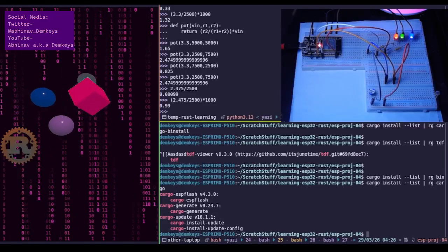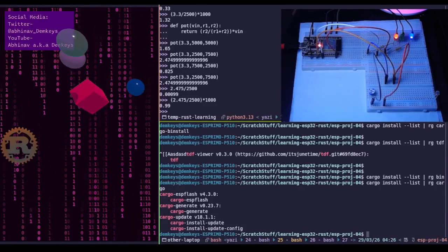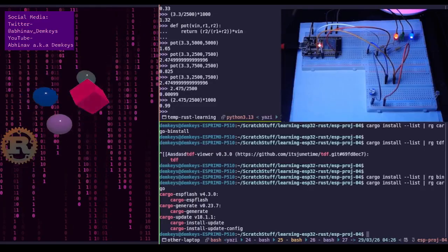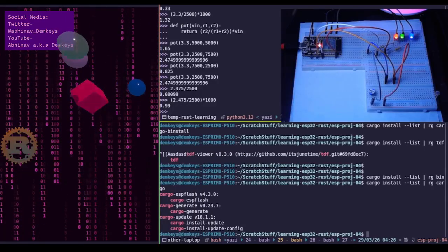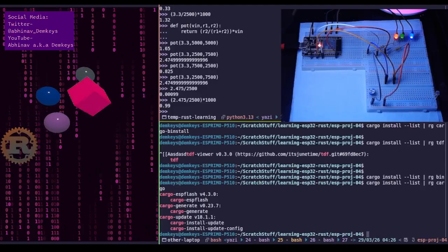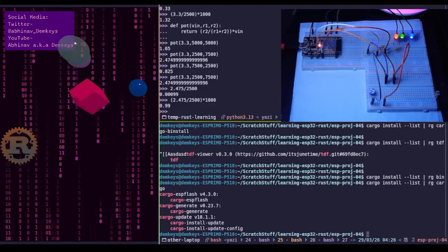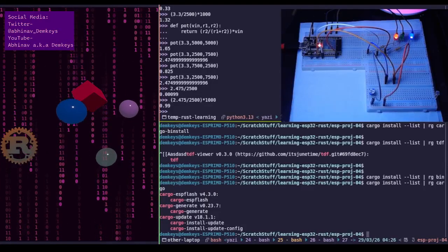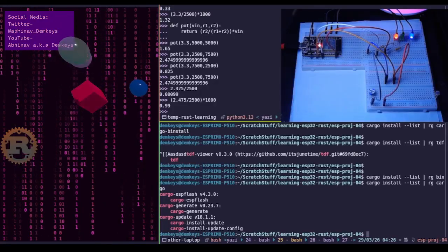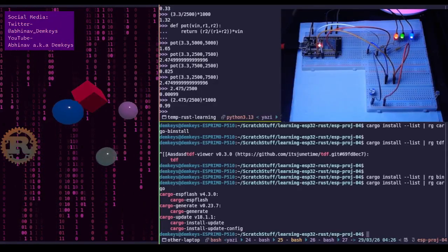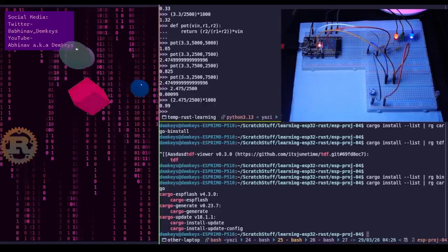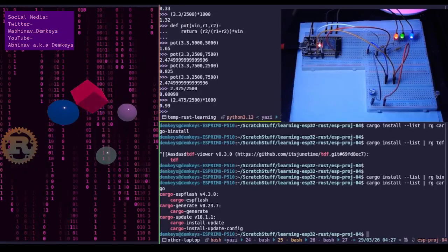Then, hello world. Quick start, hello embedded world. Before diving into the theory and concepts of how everything works, let's jump straight into action. Use this simple code to turn on the onboard LED of the Espressif dev kit. Okay, to start the project, use esp-generate with ESP32 and the project name. This will open up a screen asking for options. All right. Then here's the full code.